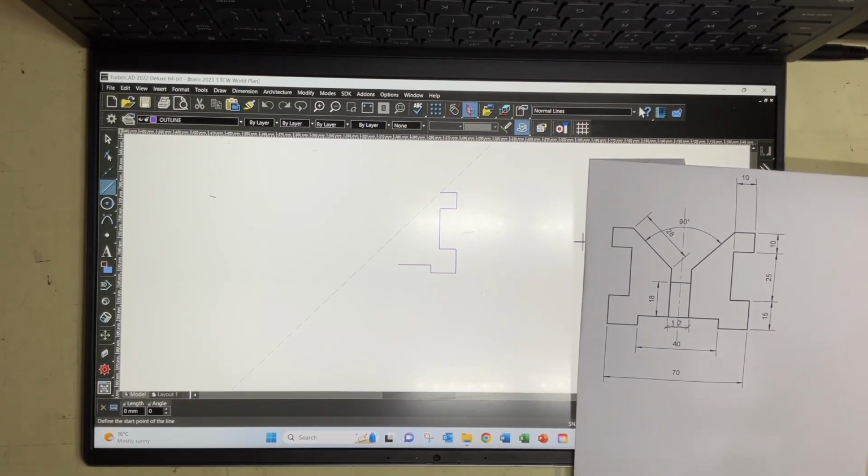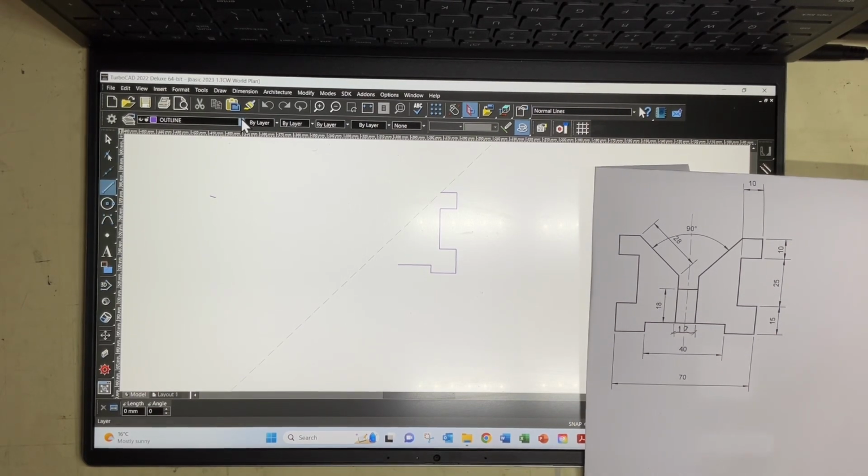Right, let's get that center line drawn in. I'm going to come up over here, click on that little arrow, find the center line, and I'm going to draw a line from that point going straight up. Now, to make it go straight up, if you push Shift, it's going to automatically go in that straight up direction over there.